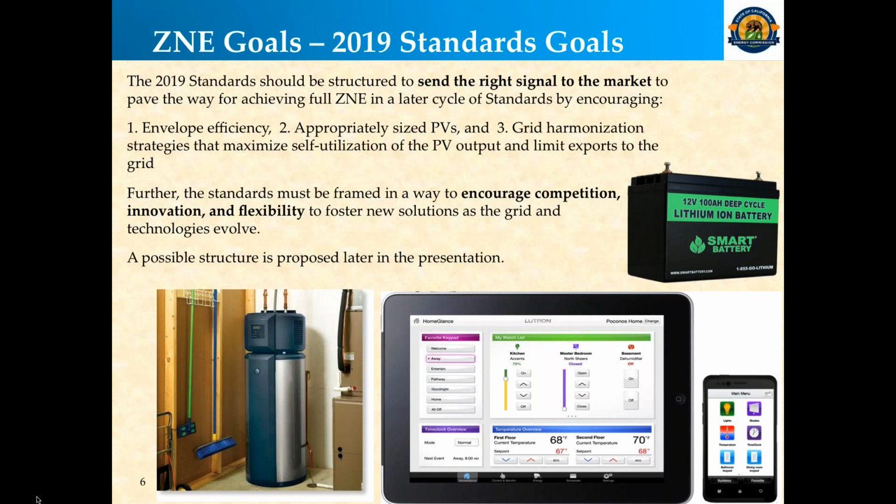Another thing is we talk about the battery, but also the idea of smart controls for the house to give feedback to the consumer so they understand where their uses are. But it also ties into demand response. If you are working with your utility to find out what their problems are, say voltage support is a huge problem when they have a lot of renewables, then they may have access to behind-the-meter battery storage for voltage support.